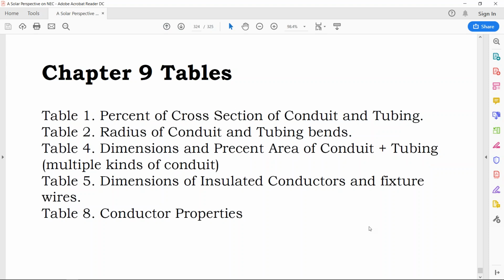When you bend 1 inch conduit at 90 degrees, it's always going to be a specific dimension. So you can't just assume that you can land conduit wherever you want to. If you have to make certain 90-degree bends, you have to do some pre-planning to plan it out.